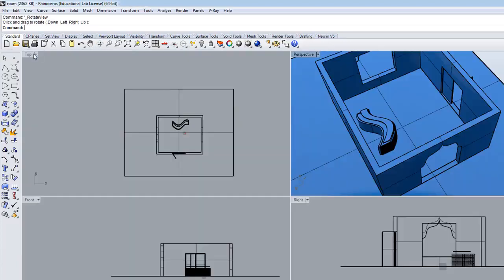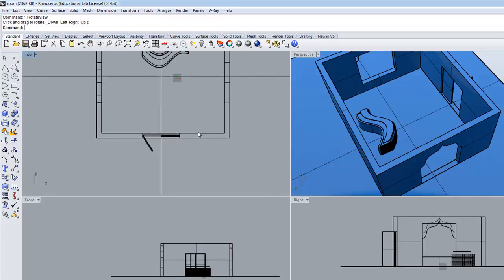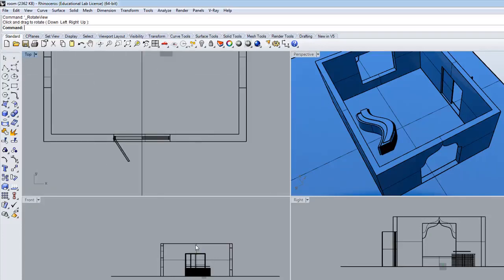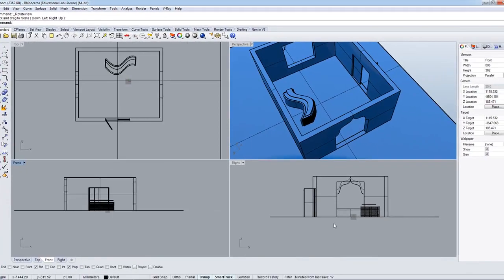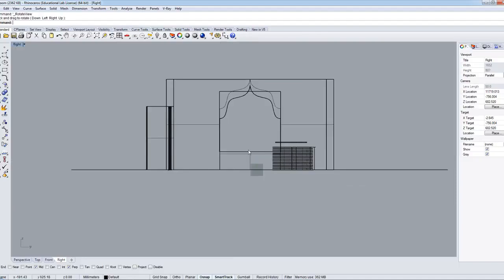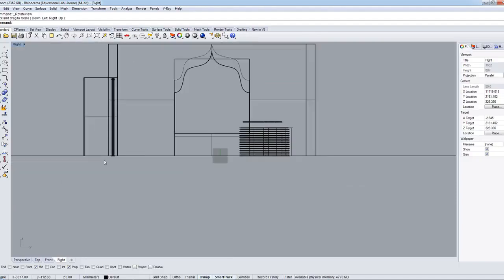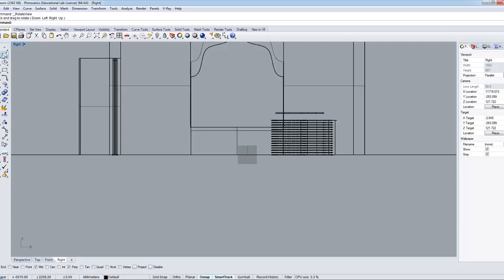build a sofa. So the tool that I'm going to use is one rail sweep. I'm going to first create a profile of the sofa, let it sweep along a rail. I think I'm going to use maybe the right view to draw, and if it doesn't work, I will change to a different view. So before I draw the whole sofa, I would first decide roughly the size.